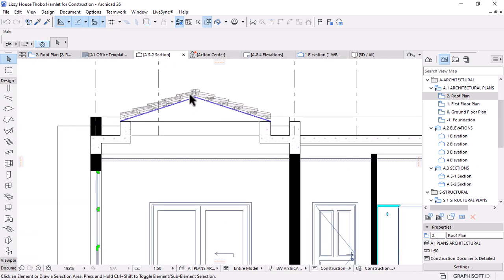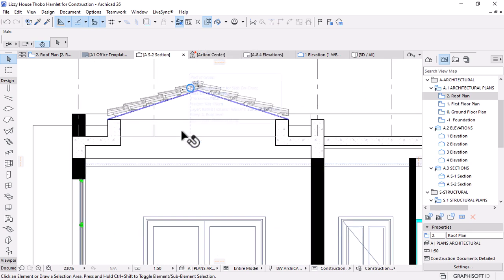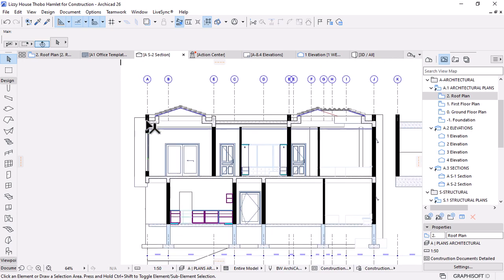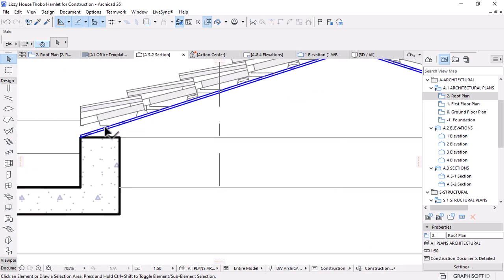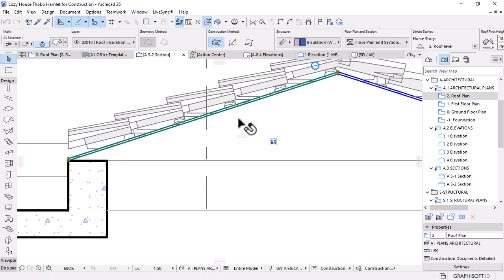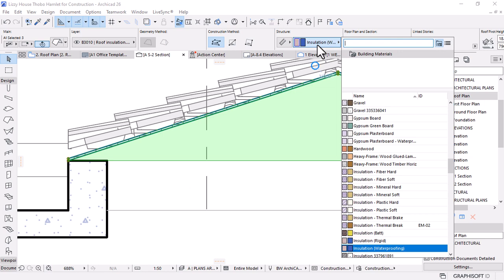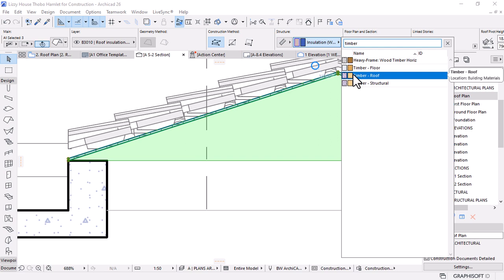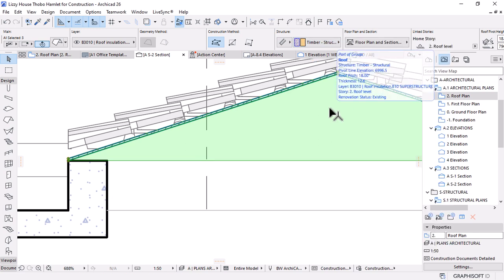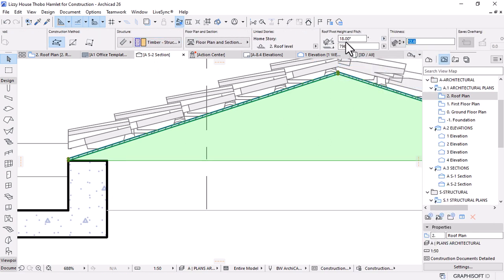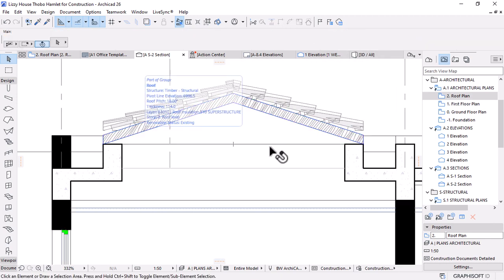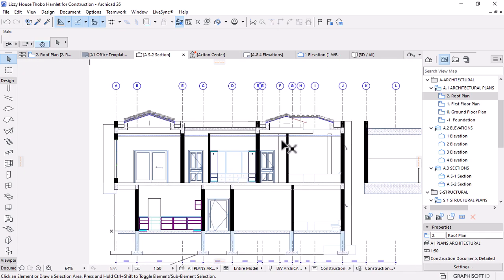And then one thing that I've mentioned is the roof structure. You can use the truss maker to further detail your roof structure, or in this case I can just take advantage of the roof. Let me group it and show you. Turn this to a timber, I'll say timber structure, right, and then let's set the height to size of timber, which is 1:5. It will be like that. Now it's a bit more like it.